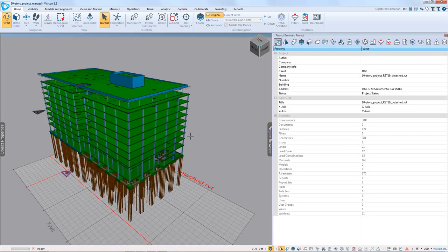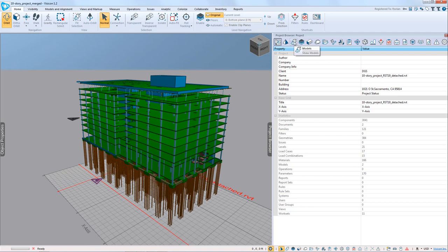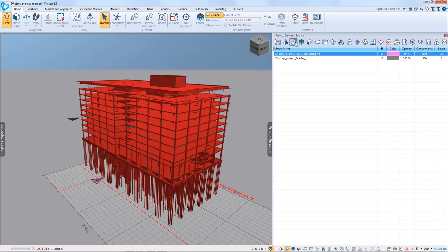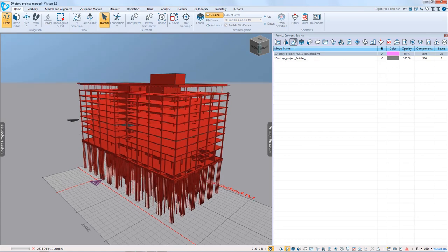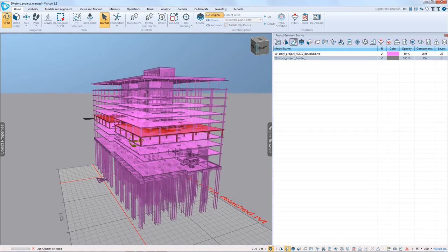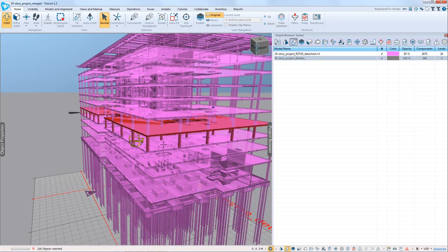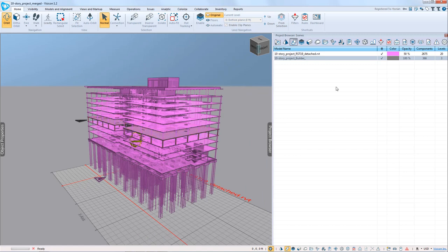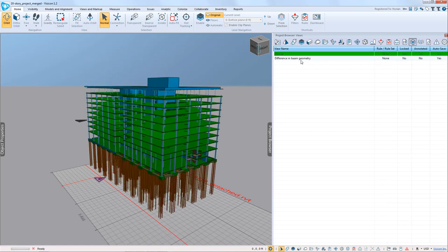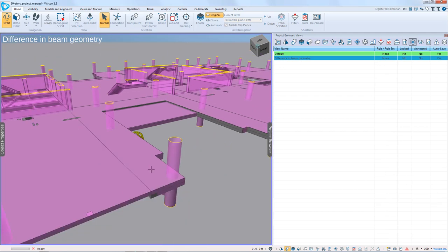On the right side, I open up the project browser, and we can see under levels, under models, this is the Revit model, and this is the adapt model. And you see I've merged in and aligned the adapt level 5 model with my Revit. I'd already gone in and created a particular view, which is isolating level 5 using the clip planes again.